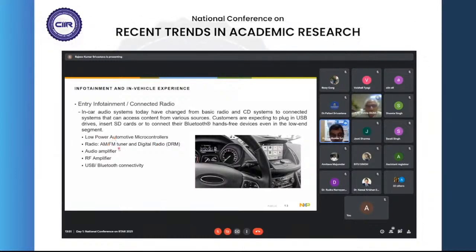So the advantage of this is that this digital radio has a quality of FM in terms of sound quality, because in FM radio, you don't see any noise because it's frequency modulated, so there is no noise. But the range of FM is very less. It's limited to cities, or it's a point-to-point contact communication. So you cannot send it using your ionosphere as AM. But digital radio has a digital transmission, so the noise problem is solved. So the quality of sound is like FM, while the transmission distance is like AM. So even you can hear the radio channels of different other cities close by, or even beyond that, through digital radio.